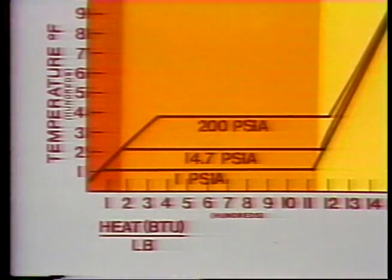In the same manner, an increase or decrease in pressure can change the state of water. For example, at this point at 200 PSIA, water is just ready to boil. If we decrease pressure to 14.7 PSIA, some of the water becomes steam. The steam is now part of a steam-water mixture in the transition zone. Decreasing pressure further to 1 PSIA, more of the water turns to steam and the quality of the steam-water mixture increases.